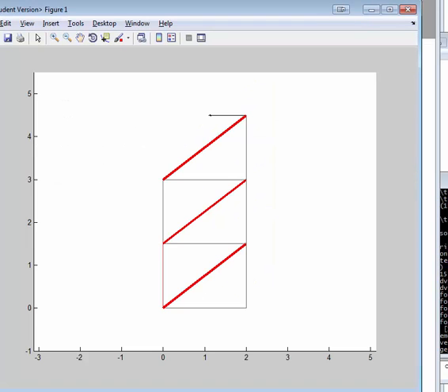And what we can see when we look at the design is that the kind of failure modes you're going to get are in tension and compression. In this particular structure, the things that would fail immediately, or fail first rather, would be those three diagonal beams, with the bottom vertical beam being almost at the edge of failure.